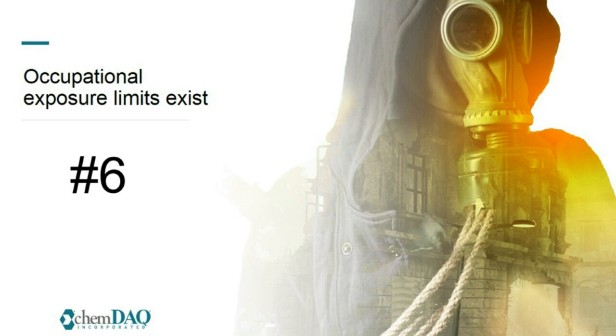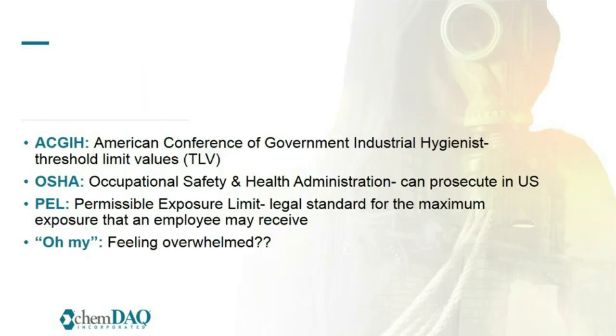Well, the ACGIH, the American Conference of Governmental Industrial Hygienists, developed threshold limit values, TLVs, in the 1940s, and they regularly updated them as data became available. There are now more than 700 chemicals and physical agents listed. The ACGIH is a private organization, so their threshold limit values are not law, though the laws of some countries actually reference them directly.